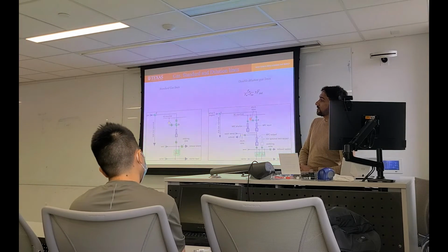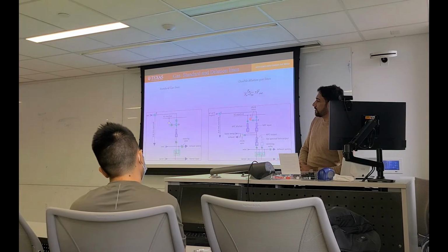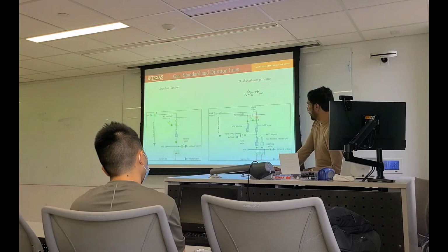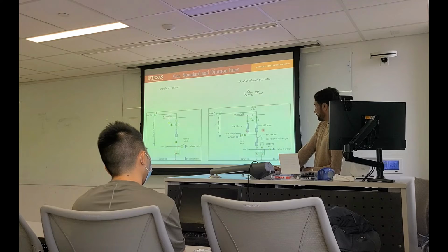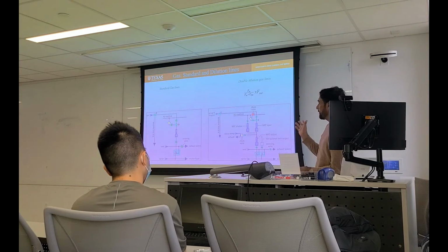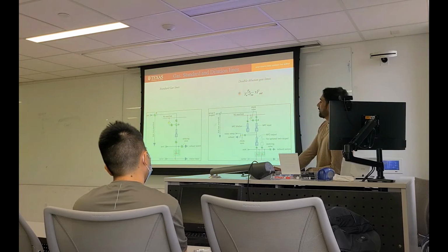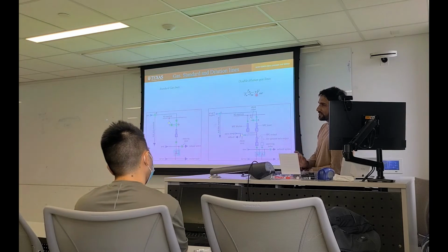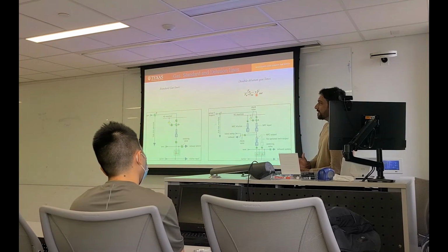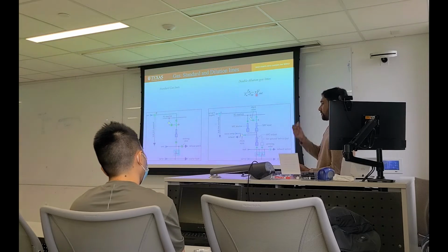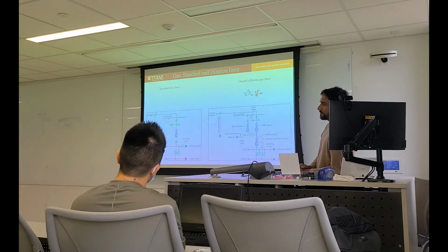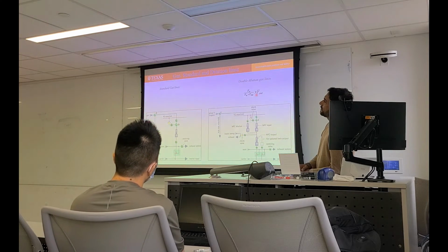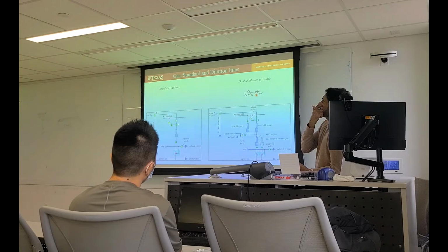We were using hydrogen for dilution. So for dilution, you should have a separate dilution MFC. There is a separate formula also. You can control whatever amount you want inside your reactor. Actually, SCCM is not a standard unit. You should mention molar flow per minute. Antoine's equation is used to control the bubbler pressure.